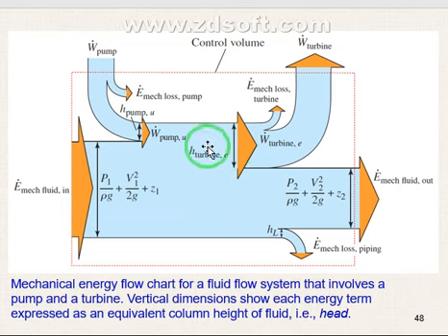This turbine will abstract this amount of energy from the flow, but at the output there are some losses, so we can't benefit from the total energy already abstracted from the flow, right? So at the end of the day, we will also have another HL here. It's the mechanical losses from these three terms, for friction, for everything. If we have a valve, if we have tees, etc. So this figure is very interesting, and will help you to understand the general energy equation.